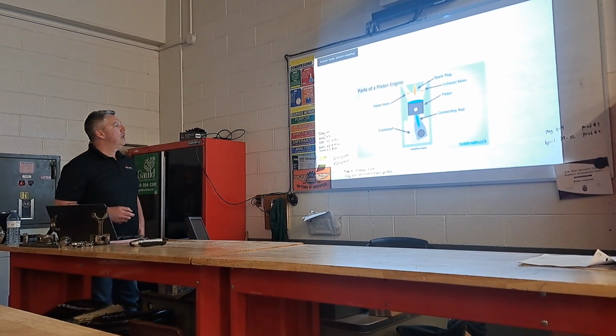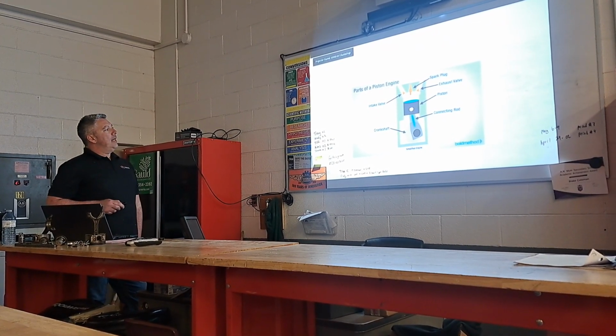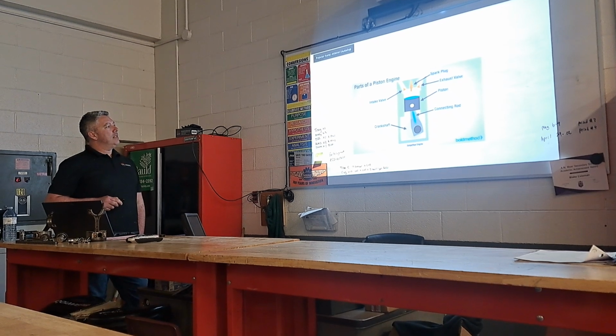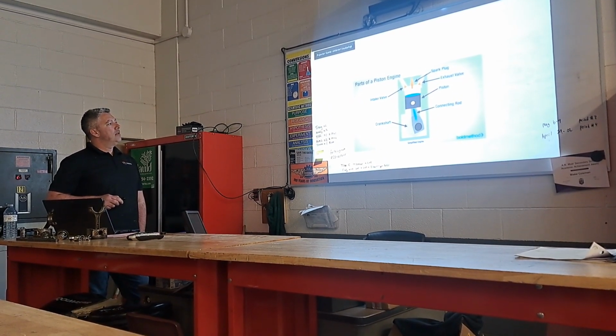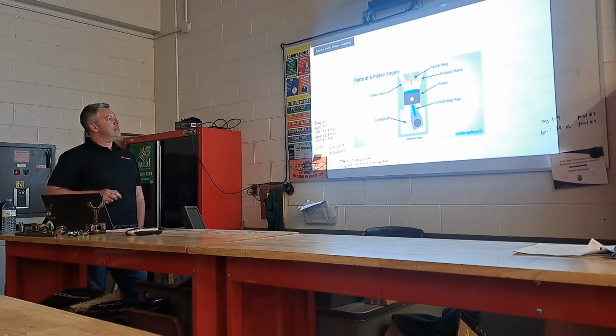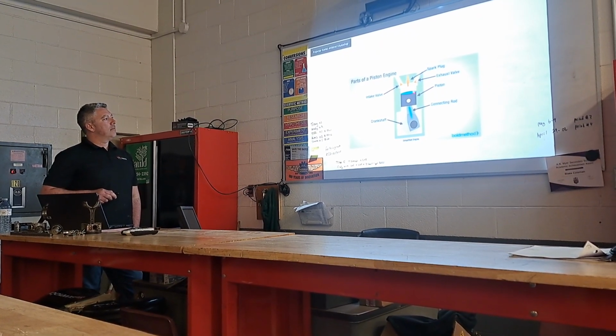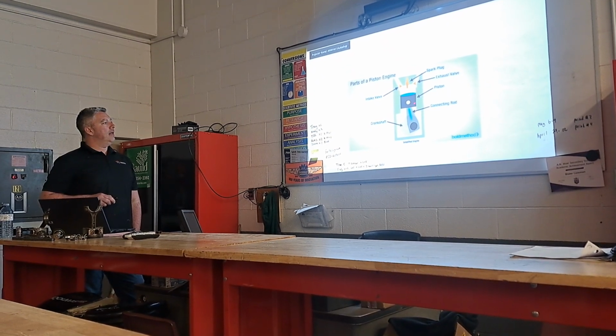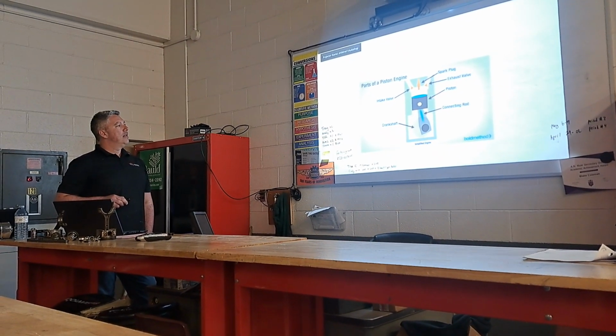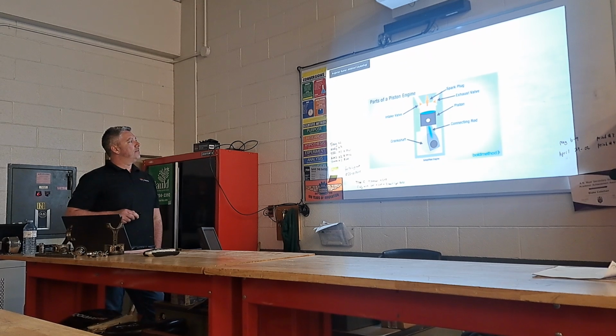Another picture of it. So, intake valve opens, allows air to come in there. At the same time, the injector squirts fuel in there. Piston comes up, spark plug ignites, piston goes back down. That's called the compression stroke. We'll go over that in a minute. Okay, connecting rod to the crankshaft, that's the piston, exhaust valve.